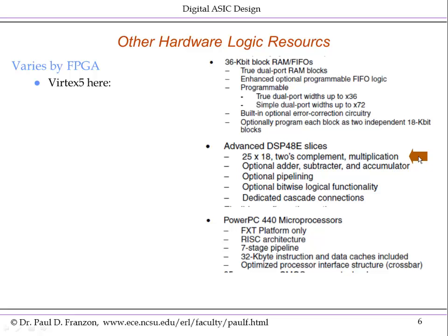If you configure it as a 20-bit multiplier, then you'll actually end up using an array of CLBs to build that larger multiplier, which will take up a lot more area than this DSP slice, and furthermore will leave this DSP slice wasted. So a big part of you efficiently using an FPGA is simply to structure your code so that it can map directly onto the resources that are available.